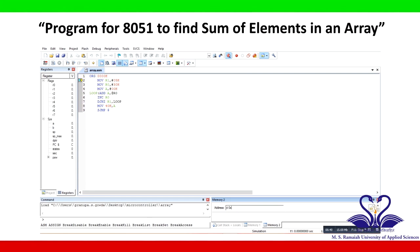D:0x30. Give enter, which means that D, the data memory, is chosen. Give colon, then 0x30 indicates that 30 is the memory location and 0x indicates it is a hexadecimal value that you are going to consider. So in 30H memory location, I am storing 11.